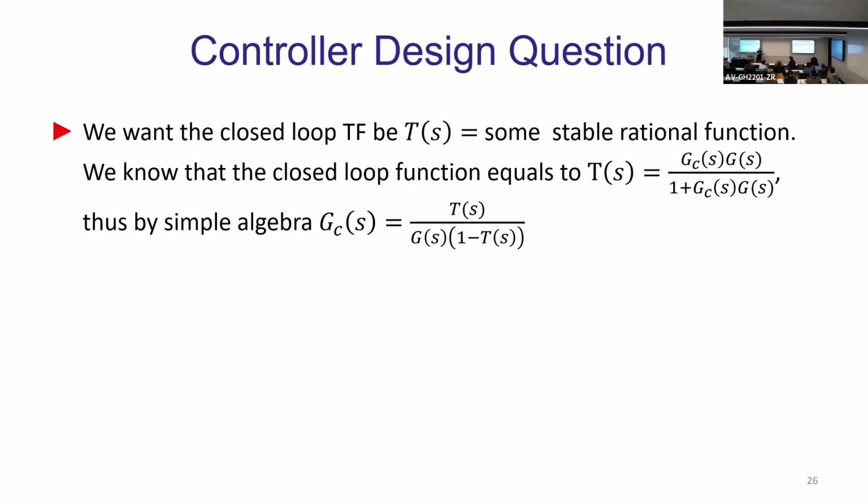Design it the way you want it, like where you want your poles to be, where you want your zeros to be, and you're free to choose them anywhere you want, practically on the left semi-plane. Farther to the left will mean that they will become faster, but bandwidth will be too. Farther from the axis will give you higher overshoot, closer to the axis will give you lower overshoot. You have all kinds of things that you can play with, but practically just design where you want the poles to be in closed loop, put them in that formula, done. What's wrong with that?